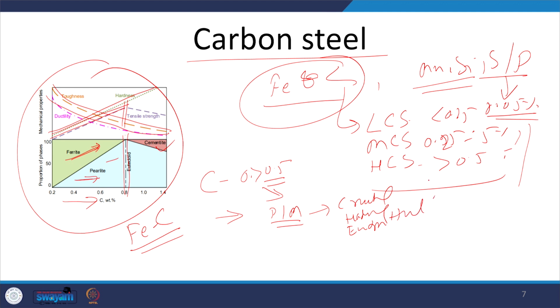Okay. So, if the carbon content in the steel is less than 0.4, then using suitable preheat it can be welded, moderate preheat it can be welded. If it is less than 0.2, then certainly the welding is easy, like in most structural steels. If it is 0.2 to 0.5, then using suitable preheat it can be done very easily depending upon the thickness. But if it is greater than 0.5, that makes the welding difficult and requires extra precautions in terms of not just preheat, but use of suitable filler metals, post weld heat treatment, etc. About these things we will be talking in detail now.